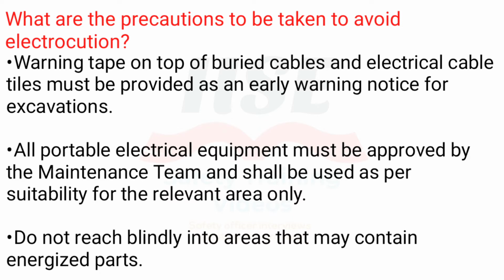Warning tape on top of buried cables and electrical cable tiles must be provided as an early warning notice for excavations. All portable electrical equipment must be approved by the maintenance team and shall be used as per suitability for the relevant area only. Do not reach blindly into areas that may contain energized parts.